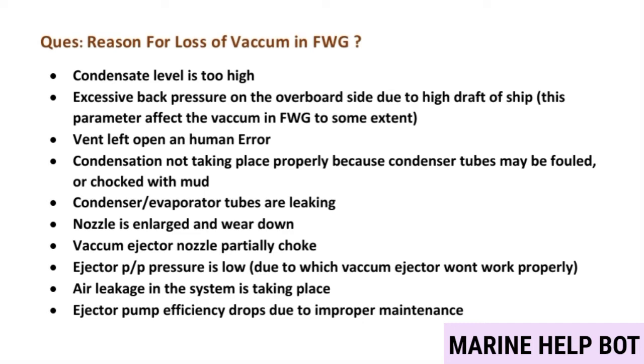Air leakage in the system is taking place. Ejector pump efficiency drops due to improper maintenance. For the leak test, I have attached one more slide at the end of this video, so please watch this video in full.